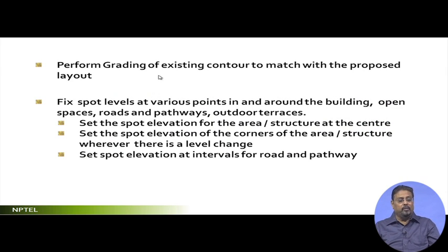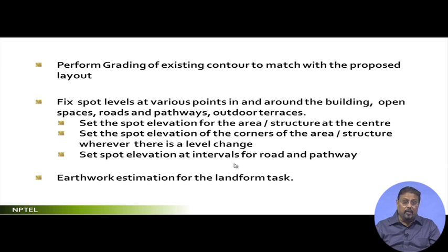And perform the grading of existing contours. Basically, this is a part of this itself. The grading is the activity in which you are fixing the spot levels, and then after that you perform earthwork estimation.